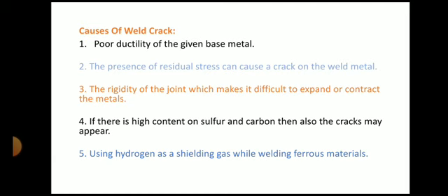Then the rigidity of the joint, which makes it difficult to expand or contract the metal. If your joint is very rigid, then during solidification the metal tries to contract or expand, and in that case the rigidity of the joint makes it difficult to expand or contract the metal. Then if there is high content of sulfur and carbon, then also the crack may occur. Then using hydrogen as a shielding gas while welding ferrous metal. So these are the possible causes of weld crack.